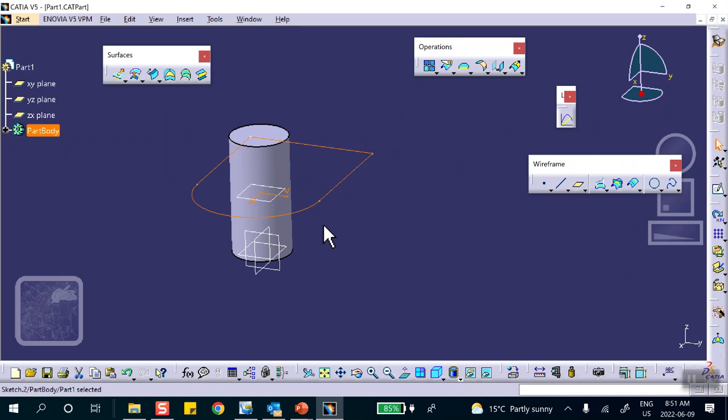This is the border of my sketch. I want to put a surface on that, and that can be done. What are the types of surfaces that we have created? We have created extrude: you draw something and then extrude the curve in a certain direction. We have done revolve: draw something, revolve it, like a shaft. There's another one: if you have a closed curve like that, you can put a surface through it.